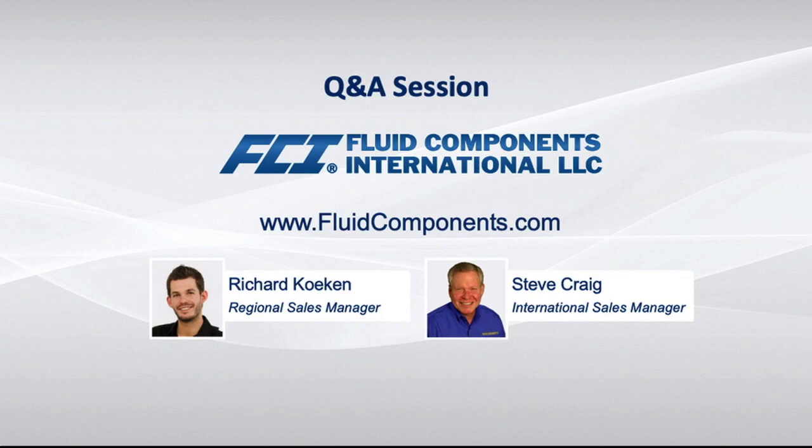Excellent question again. So the total application measuring uncertainty, as we have demonstrated during the presentation, is depending on many factors. To answer the question shortly, the answer is no. For example, if you have a 4-inch line size and you have 8 measuring points, that does not mean that you have a higher accuracy compared to 1 point. As explained during the presentation, there is an optimum number of points available for each line size, and please consult with your manufacturer to determine the optimum number of points for your application. So hopefully that will address the last question of today.